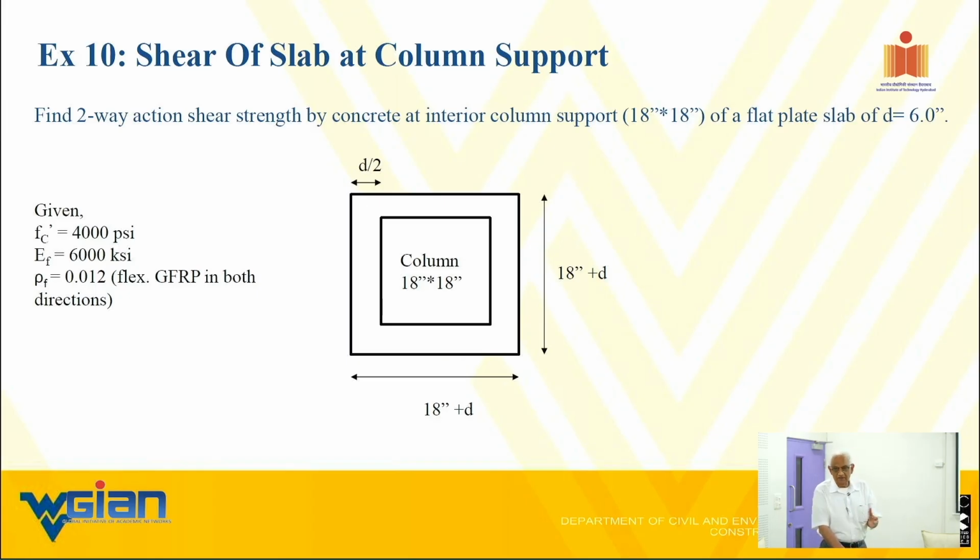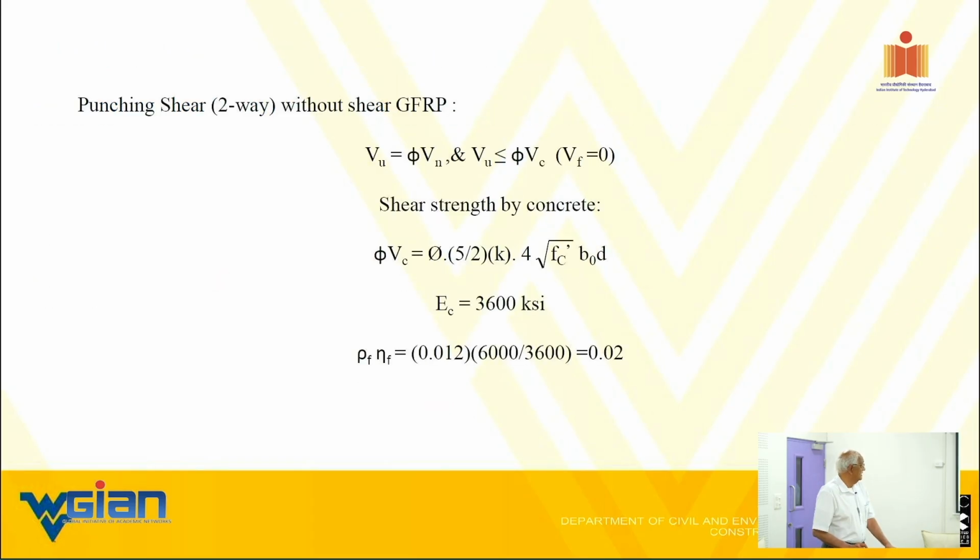That's very standard, everybody accepts it based on your 45-degree angle. That's where it comes from actually. So again, these are just some numbers. We are keeping it consistent. The plate thickness effective is 6 inches. Probably the total depth is 7.5 inches.